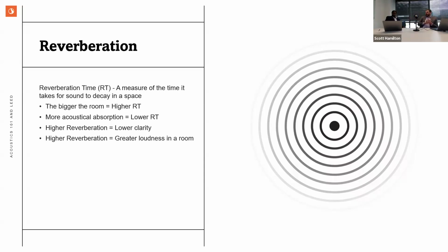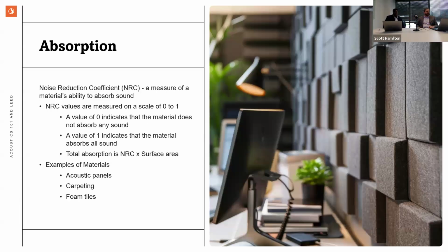The best analogy I have for that is we all probably played outside as kids, came inside, and one of our parents told us we need to use our indoor voice. We were so used to adding all this extra effort to talk outdoors to cover a longer distance, without all those reflections building up the apparent loudness within a space. We come inside, now we're way too loud, and suddenly we're talking at such a high effort because we're used to it. That's partly because the room loudness is adding to the apparent noise level, or sound level in this case.